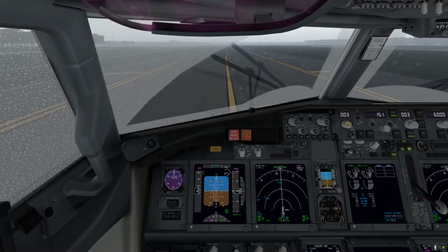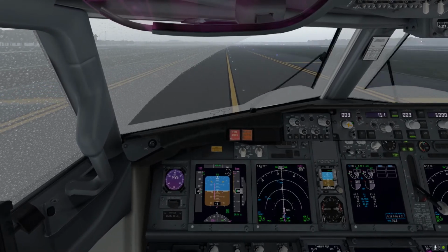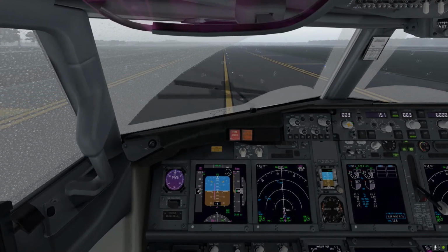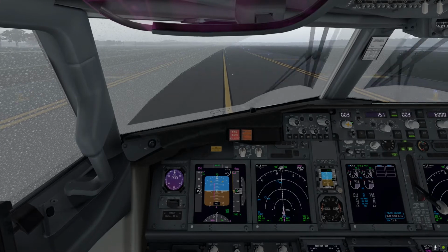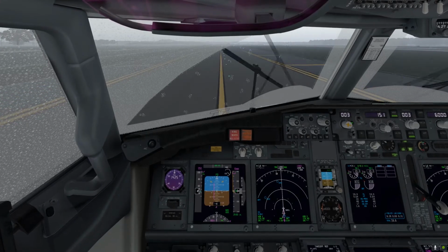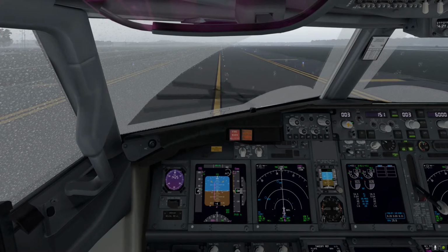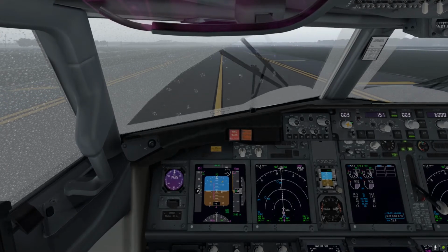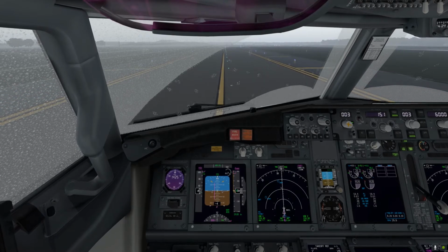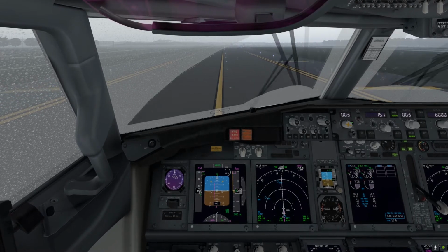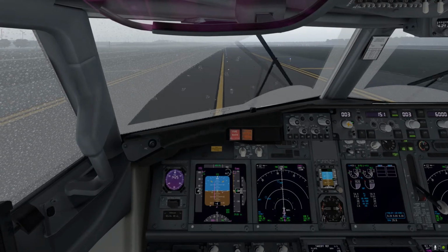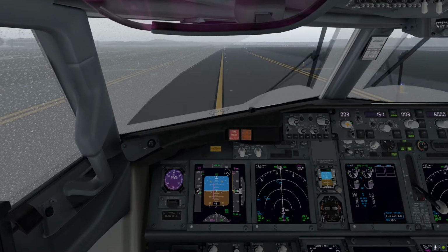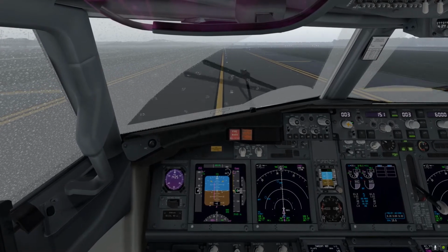We have about 478 meters stop margin using runway 01 left, which can be increased up to 900 meters if we use a non-derated thrust. So that's exactly what I'm going to use and to do. I will use still runway 01 left, also not to put the ATC in a very uncomfortable situation.